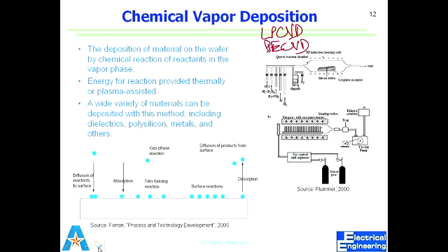So you're actually keeping the plasma energized with RF? Because whatever you are creating is getting consumed, going down on the surface. I see. How do you get the plasma started? Do you have to ignite it? It's not like switching on a button. Yeah, so you start with low energy, and you have to pump the power gradually to the level of whatever your recipe wants.